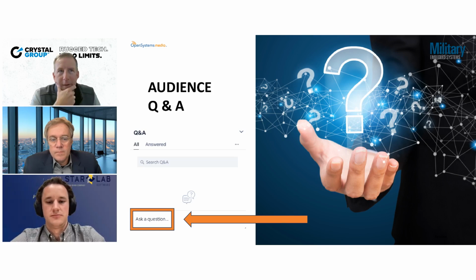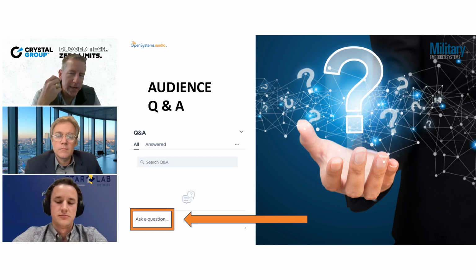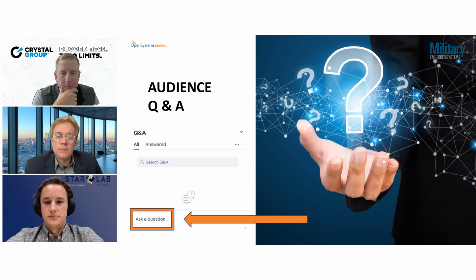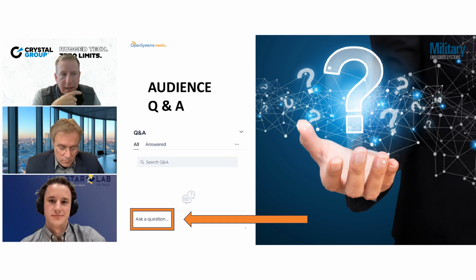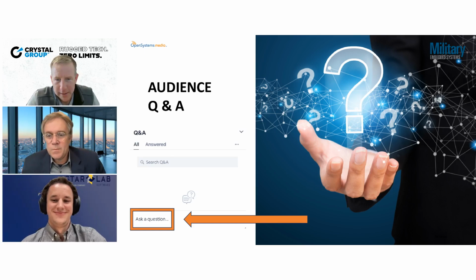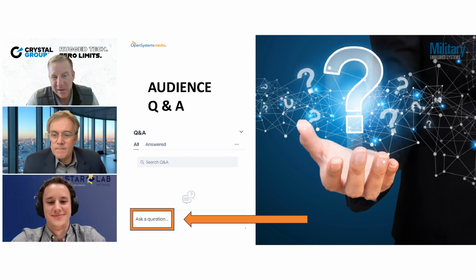So the short answer is it depends on the vehicle itself. What you've got to do is flip it around and say, we know we're going to have these in aerospace, surface vehicles, ground vehicles, subsurface, that kind of thing. So what we as integrators and designers have to do is figure out how to modularize that I/O component, separate from your core processing, GPU, and memory, and not burden a ground vehicle with a bunch of MIL-STD-1553 that they're never going to need. But they do need the CAN bus. They absolutely need fiber, maybe more than copper.